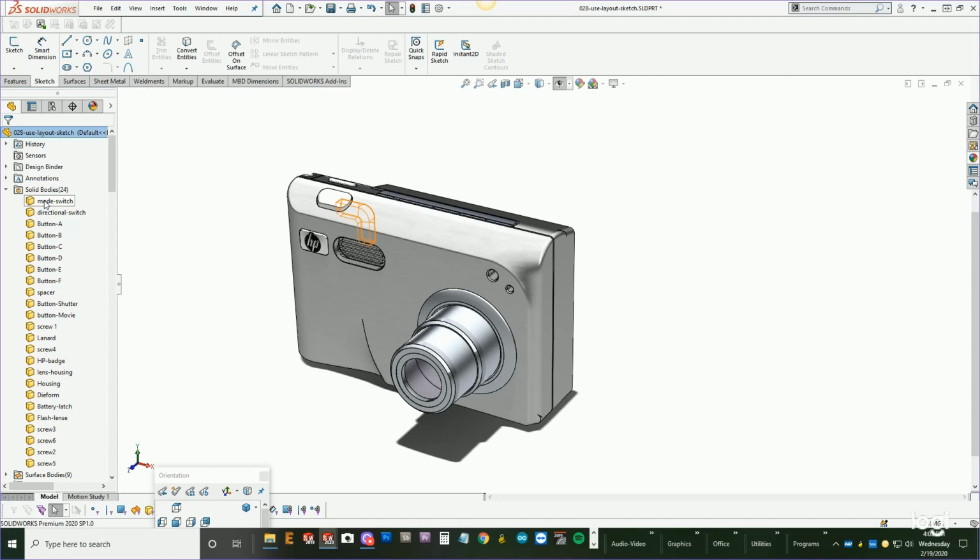This is important so that you can find those features quickly or isolate the body so then you can work on it. But it's also important when you export this, either IGES or STEP, those body names come through into the import of whatever system it's going into. So that's important information for people who are on the receiving end of this work.